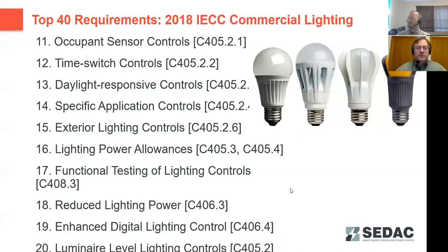So again, just to cover those and clarify, if you're using spray foam in your buildings, be very careful that the depth of that insulation is going to meet your air barrier compliance depth. For closed cell, it's 1.5 inches or deeper. For open cell, it's 4.5 inches or deeper, or consult your manufacturer's installation guides, because we've seen some that are 5.5 inches or deeper. And for windows, make sure your code officials get those compliance certificates and window labels.